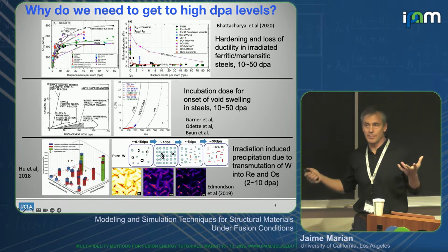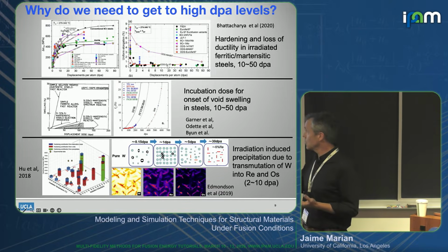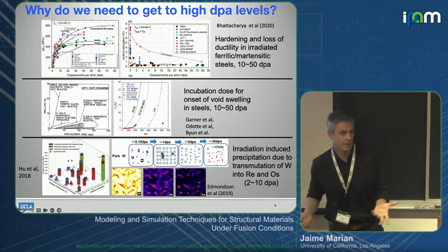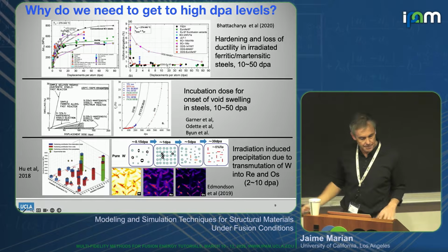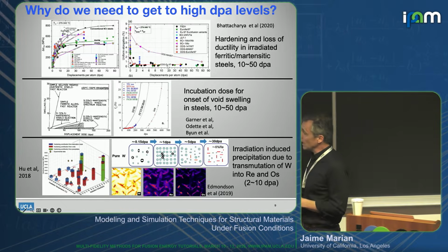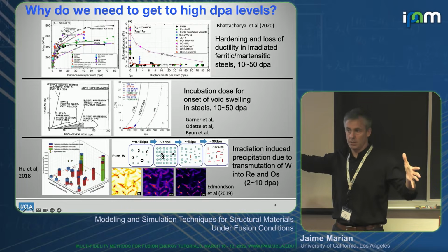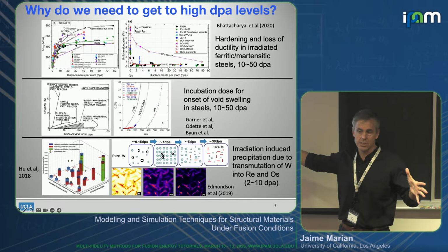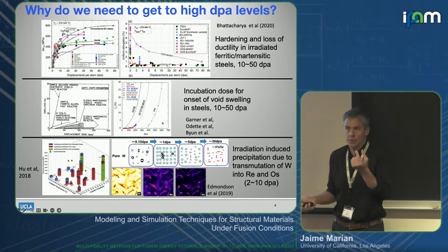Okay, we don't have a fusion material at the moment. The fracture toughness goes down, meaning it's going to behave like a highly brittle ceramic, steel. And we use steels because they're very tough, right? They don't break. Also, they swell, so they will literally swell. They will irreversibly, not like elastically, but they will increase their dimensions irreversibly, which means that when you're looking at